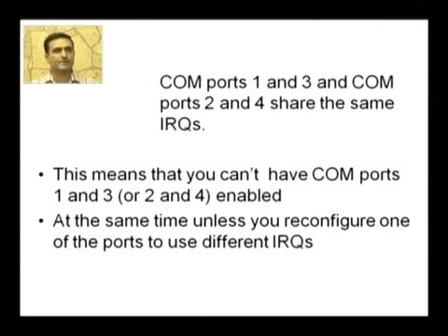I have said earlier that COM ports 1 and 3 and COM ports 2 and 4 share the same IRQs. This means that you cannot have COM ports 1 and 3 or 2 and 4 enabled at the same time, unless you reconfigure one of the ports to use a different IRQ.